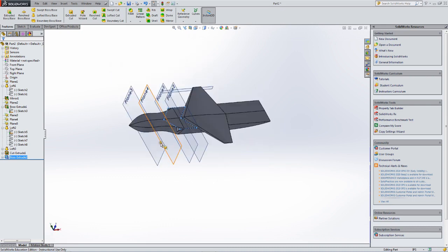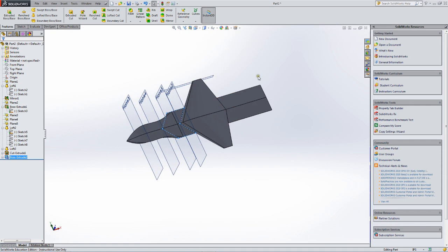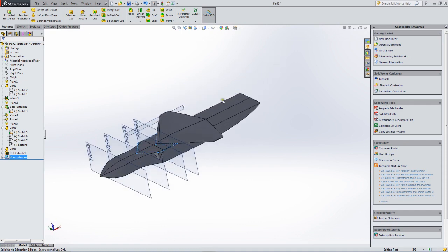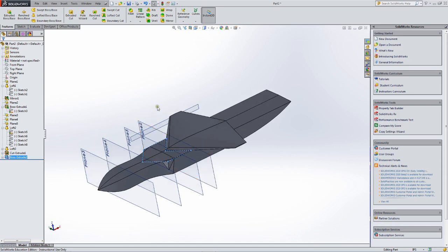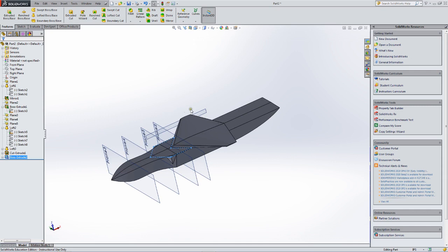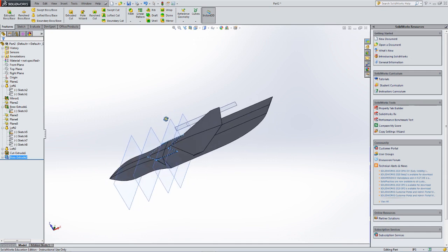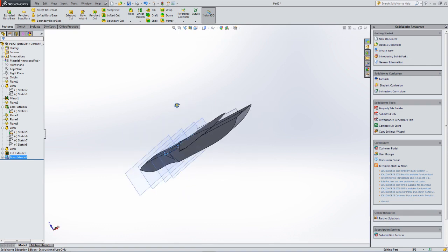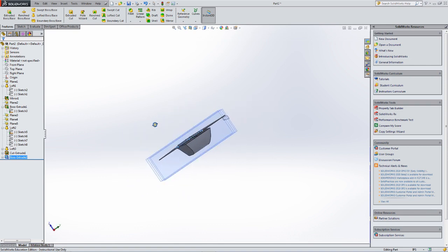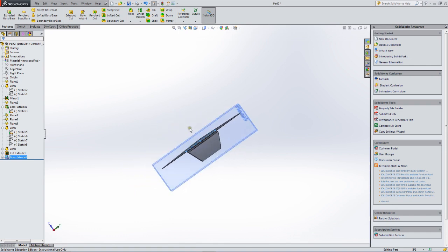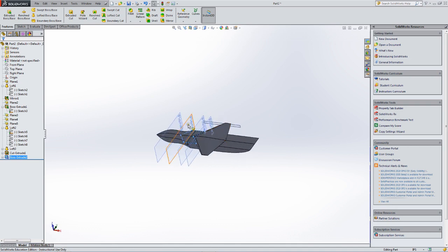fuselage drawing. Only thing left to draw are the butterfly tails and other changes to prepare it to be a wind tunnel model. But what we've shown you here are the basic functions that you need to be able to do in SolidWorks. I'll show you just one more thing. I'll show you an extruded cut to show you how we might make a hole for the engine.